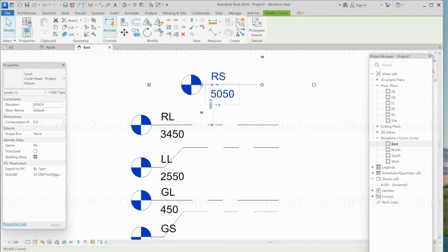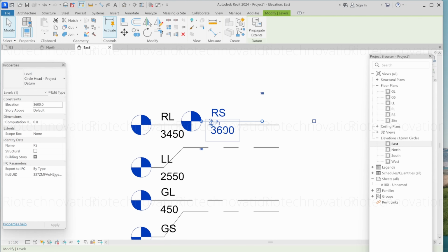Now what we are going to do is set the level. So this thing we can set. There are so many options. Whatever method we are selecting is important. So in this case, I will click this option. The height from roof level to roof surface, I will say again 6 inches, which is here I see things. This is not the ground level to ground surface. This is not 6 inch. I think I pronounce it like 6 inches. It is 450, means 6 plus 6, 18 inches. So here it is 6 inches, which is 150 mm or 15 centimeters.